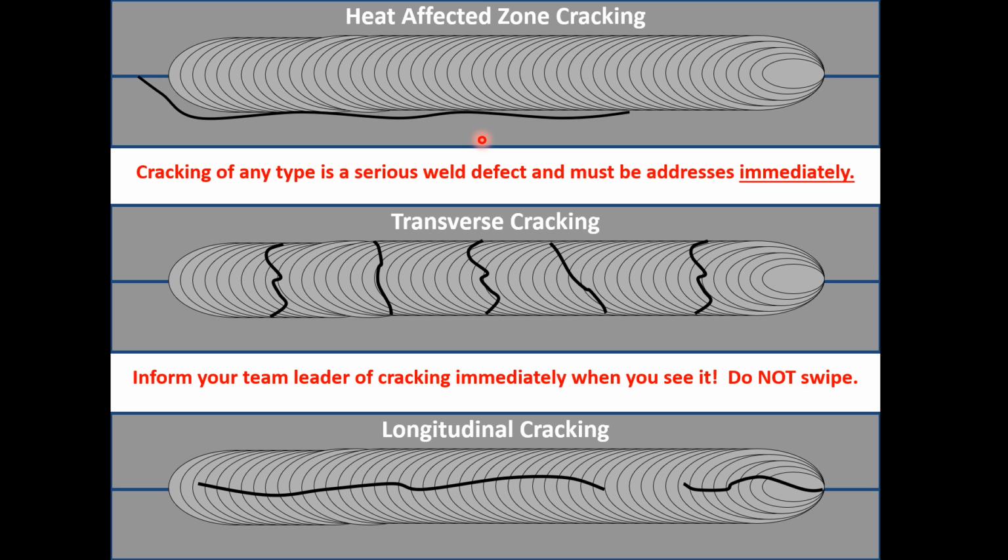Now, this one, transverse cracking. Transverse cracking usually happens as a result of a condition called hydrogen embrittlement. You might remember from some of the previous programs where I've said that hydrogen is our worst enemy, and silicon is our favorite element because silicon mops up all those impurities, does some great things. Hydrogen forces that condition called hydrogen embrittlement.